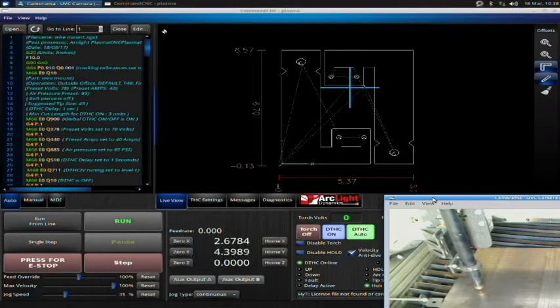Because your plasma can have lots of different cutting tips. You can have, if you say for instance you have a PowerMax 85 amp plasma cutter, well, you can have an 85 amp standard tip, a 65 amp standard tip. You can have a fine cut tip. All these tips require different settings and different amperages to operate properly.